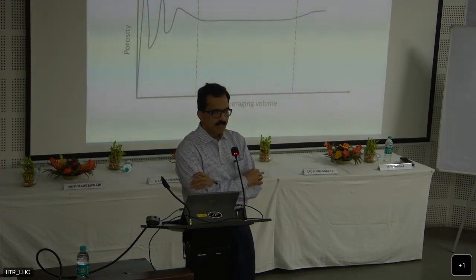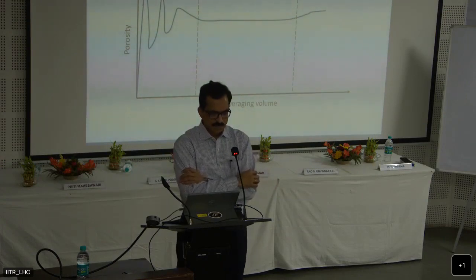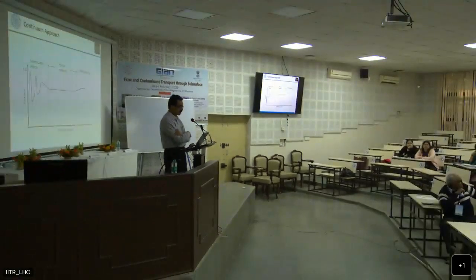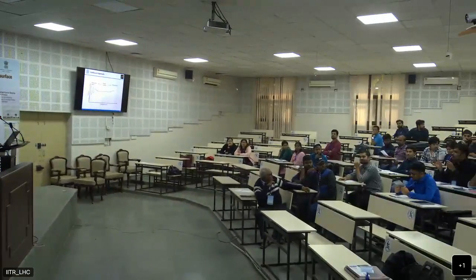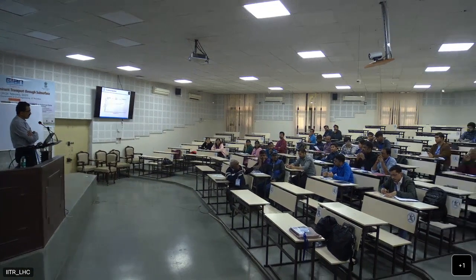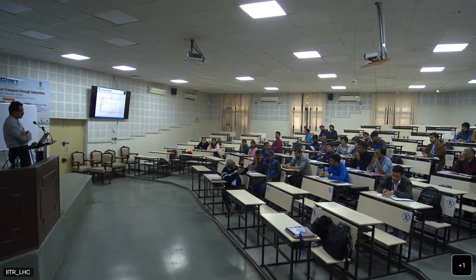You need block transmissivity, right? You should consider that, if you know the value. We will use transmissivity for the whole aquifer thickness, and permeability for unit cross-sectional area. Each aquifer is lying in different blocks, so you consider whatever block you are considering.